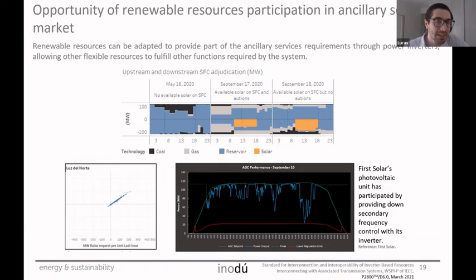There is also a standard under development for interconnection of inverter-based resources to the transmission system, developed by the Wind and Solar Plant Interconnection Performance Working Group of the IEEE, which signals that due to the response times of inverters, renewable units can and should provide not just primary frequency control, but also fast frequency control.